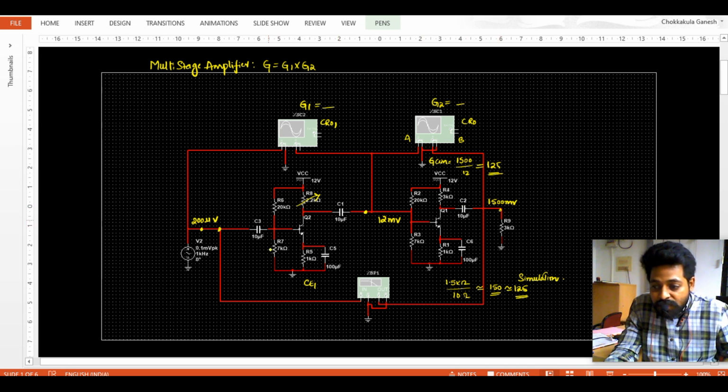But the problem with the first stage is we expect a similar kind of module here also. Maybe the resistance is small, with some deviation, but we expect the gain for this circuit to be 2.2 kilo ohms by, from this concept, pull up by pull down. So we expect 2.2 kilo ohms by 10 ohms. So we expect the gain around 220 times, because we are keeping 2.2 kilo ohms. Here 3 parallel with 3 is around 1.5 kilo ohms. Here it is 2.2 kilo ohms, right?